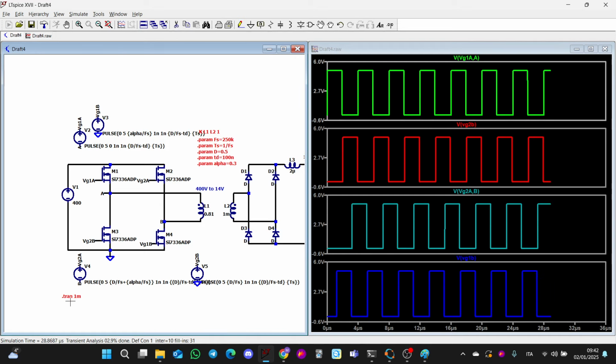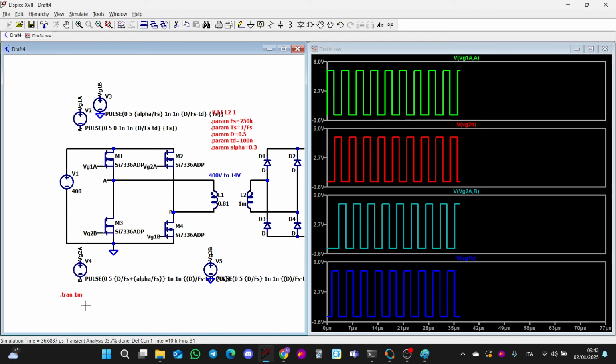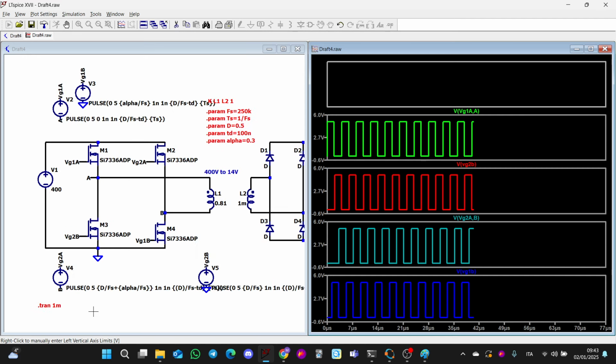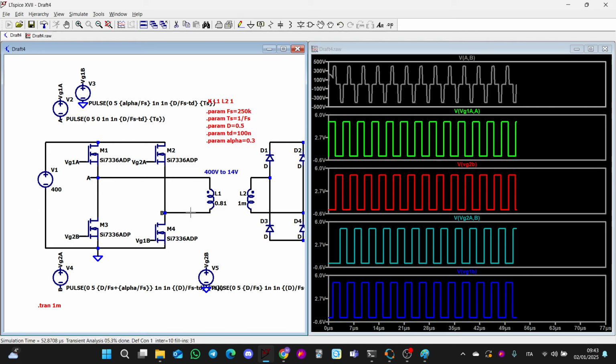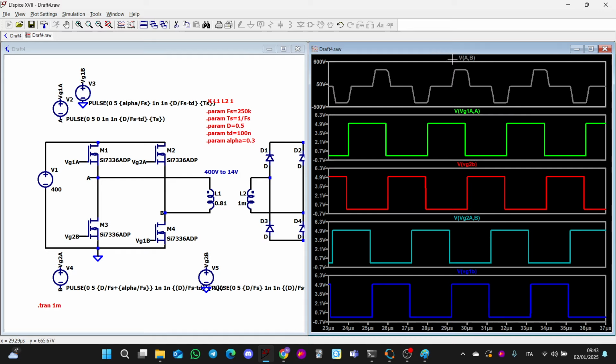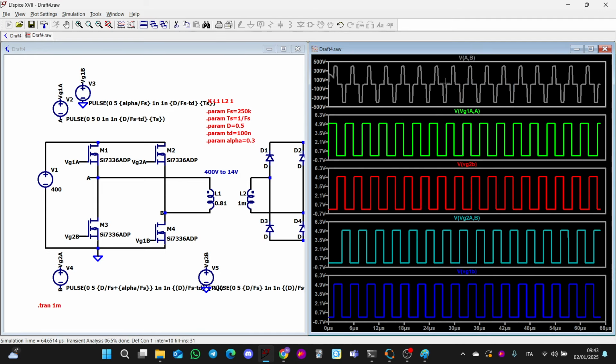Yes, the simulation is horrendously slow, and I'm afraid that it's about to crash. The simulation may be like this because we are creating short circuits. So if I see the primary voltage, okay, the primary voltage is correct because when I create the short circuit it goes to 0, as you can see. So yes, it is correct. Spice is slow because we are creating short circuits at each interval. Probably that's the reason why.